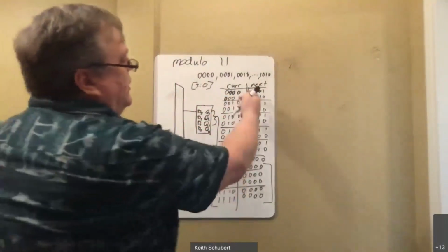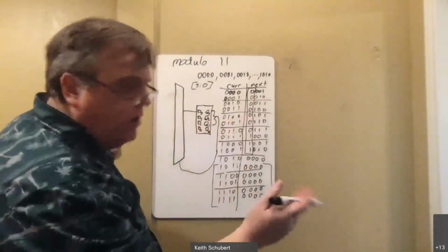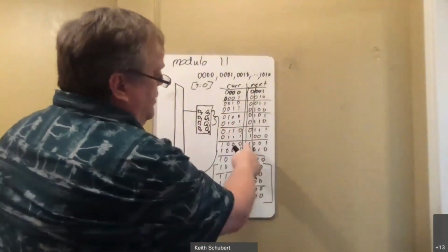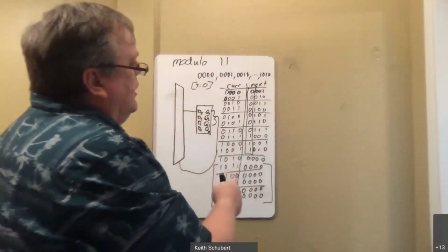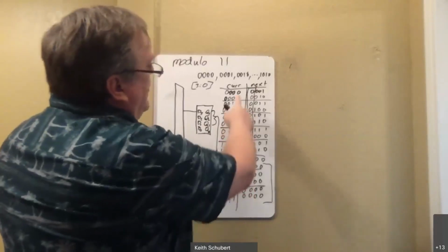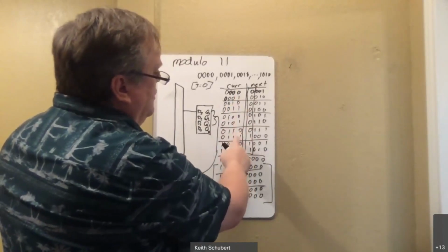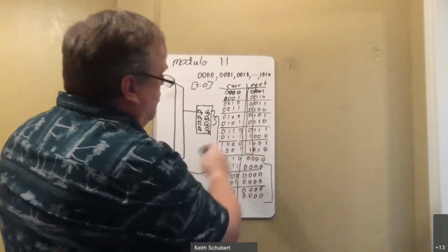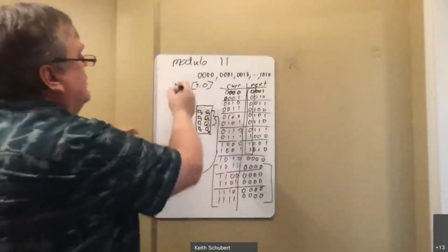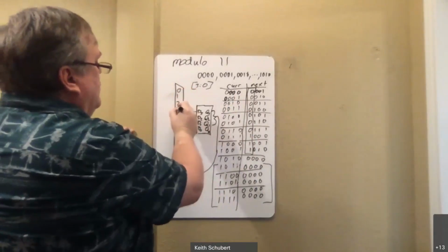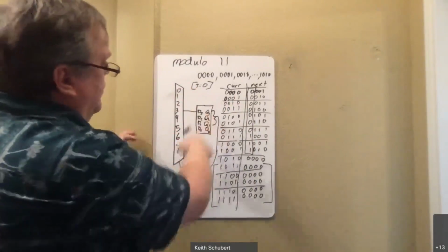And then the pattern in here will either be 0, 0, in which case it means give it a 0. It'll be a 1, 1, in which case we give it a 1. Or it'll be something like a 0, 1, in which case I give it the least significant bit, the same as Q0. So if it's a 0, 1, I give it Q0. This is just your regular mux design. 0, 1, 2, 3, 4, 5, 6, 7. That's what 3 bits gives, and that's what I was given.